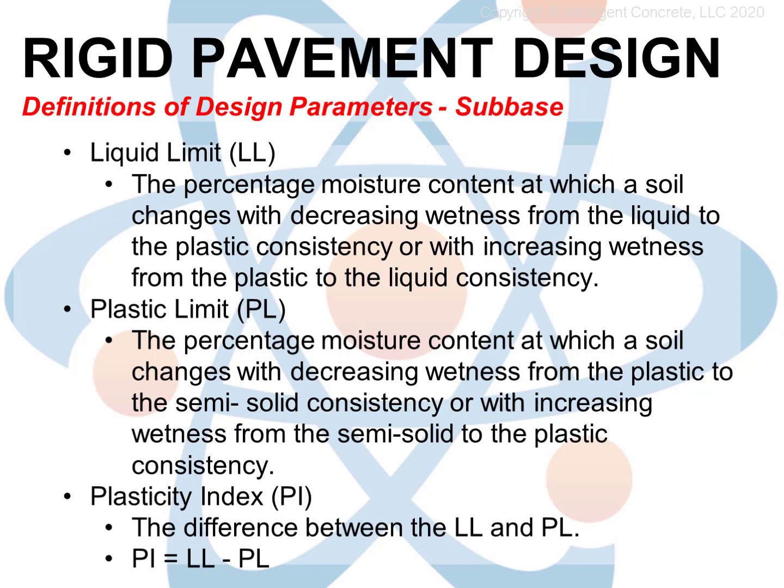Once you've gotten a so-called plastic soil to be able to be deformed into the ribbon or cylinder, and you keep adding water, the soil will begin to lose all ability to hold its shape and will begin to be mud. By weighing the soil and the amount of water added, it's possible to estimate those two parameters.